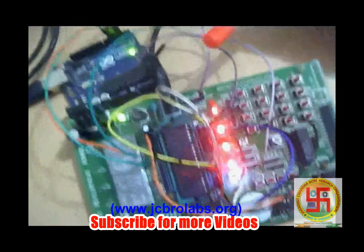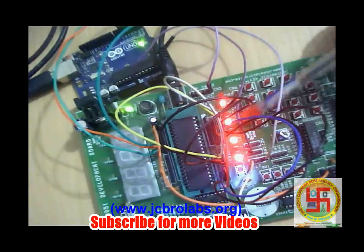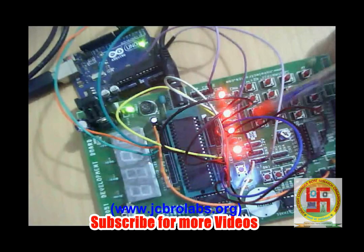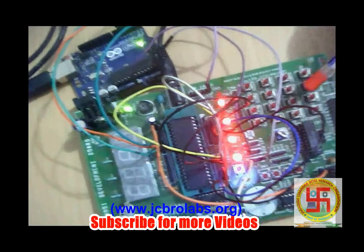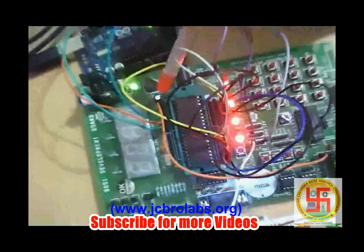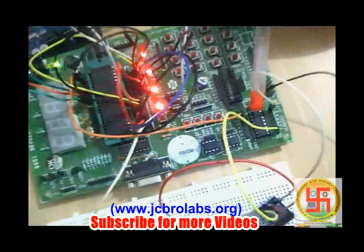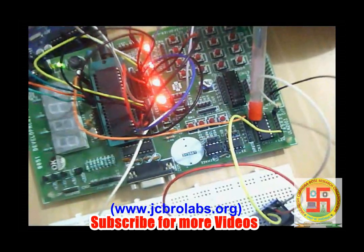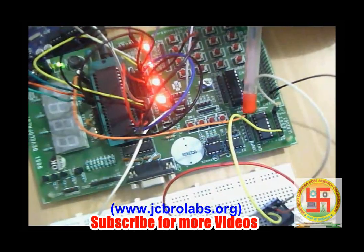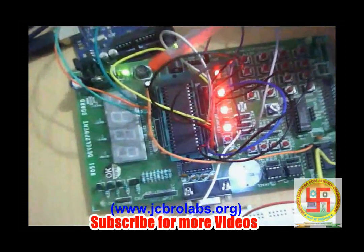Now further, for demonstration purposes, we also have connected these LEDs to port 2, and as we saw in the simulation, these LEDs will blink alternately. And this pin 1.0 is going to the ULN2003 IC. So this is the ULN2003 IC. The input to this ULN2003 pin 1 is coming from 1.0 of this microcontroller.